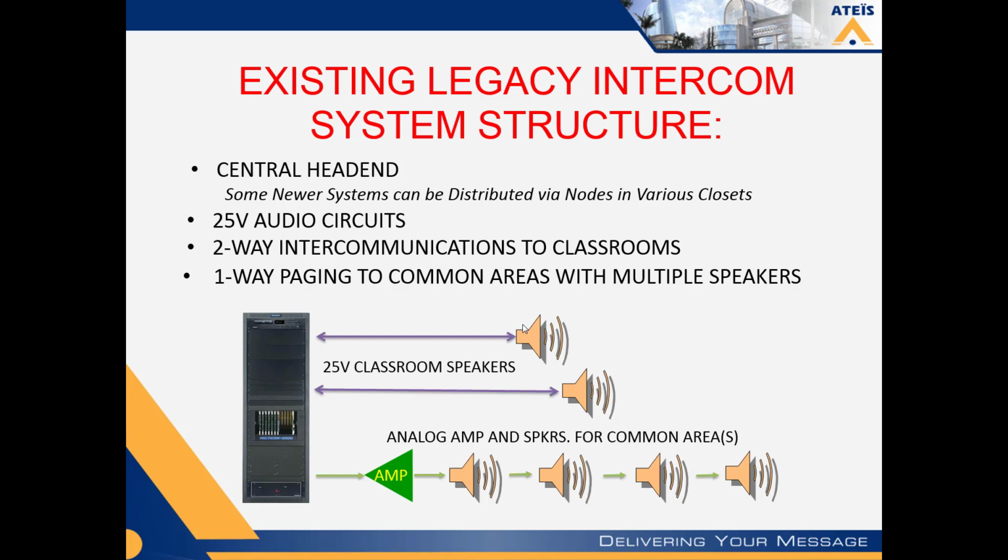They are never used or shouldn't be used for two-way intercommunications because, number one, they have multiple speakers in the zones. And number two, there's usually a ton of people and you don't know who you're addressing or who's talking back to you like you would when you dial a classroom or a specific station like a call station. So that is how most intercom systems and just about all the legacy intercom systems going back 40, 50, 60 years should be structured, at some semblance of this or variation of what you see here.